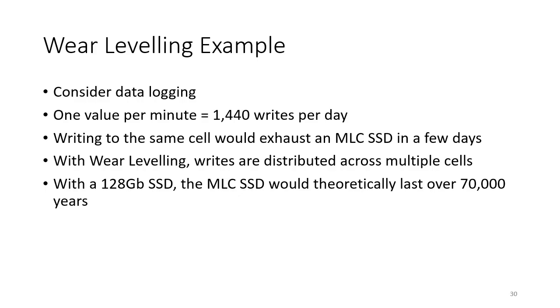Let's just have an example of wear leveling. If you're considering data logging, let's imagine you had one value per minute coming from your industrial application. That would equate to 1,440 writes per day. Now, if you were writing to the same cell, that would exhaust an MLC SSD in a few days. Imagine you had a 10,000 write capacity. Within about 7 days, you'd have written 10,000 values, and that cell would now either fail or turn to read